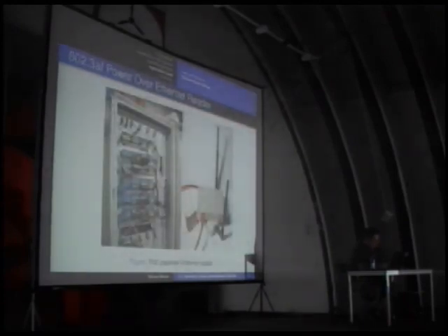These are some pictures of the installation from last year. And these are the new Power over Ethernet powered readers. You have one port where you can plug in an 802.3af compliant PoE Ethernet switch, and on the other side you can see the second port, where you can cascade multiple readers.